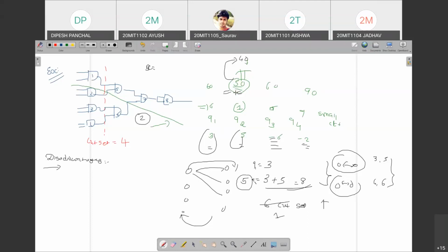So in your computer, in your software, multiple passes are running, not just one pass, because circuits are very complex in digital design. Here you are getting a minimum number because the circuit is very small. In the previous two examples, we got one cut set, the first example and the second example. While in this homework example, your cut set answer should be 2, because one is anyhow not possible if you apply any cut-balanced partition. So you have to be satisfied with this 2. Is it fine?